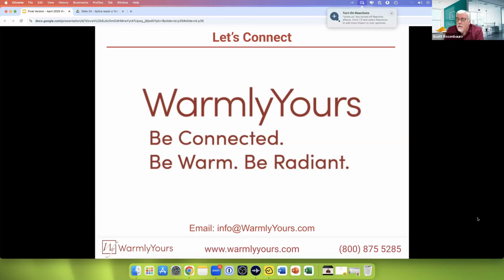The power cable, you shouldn't do any splicing of the power. If you're talking about the non-heating lead, the non-heating lead from the heating product has to be run into a junction box in that room. And then you can add whatever you want from that junction box, say back to a breaker panel. Always check your local code to see if you need to have a disconnect in the room that the heat is located in.